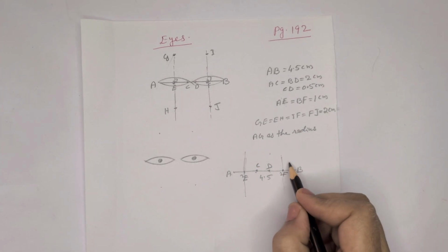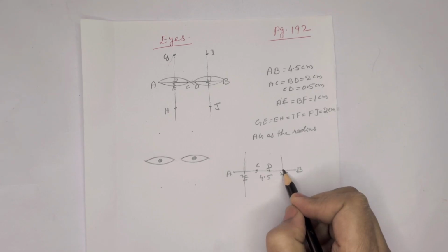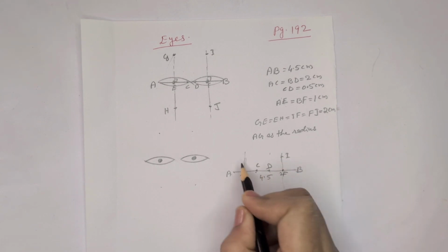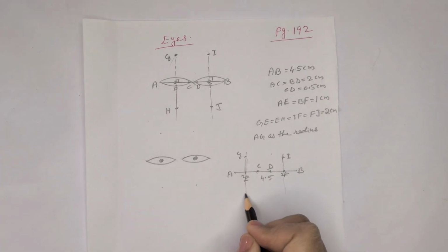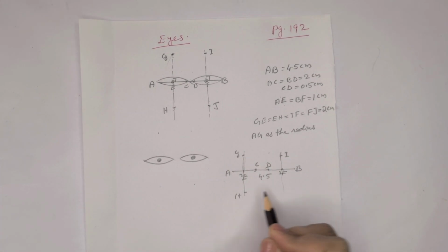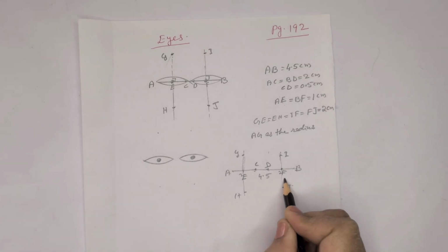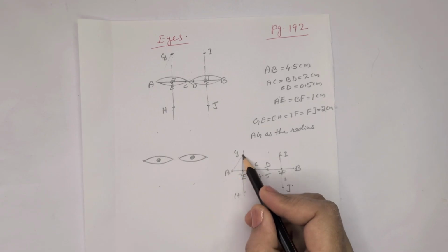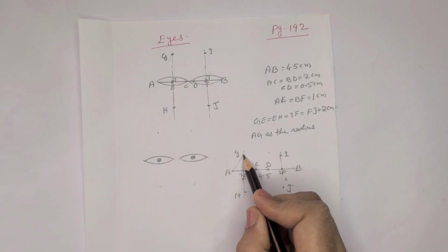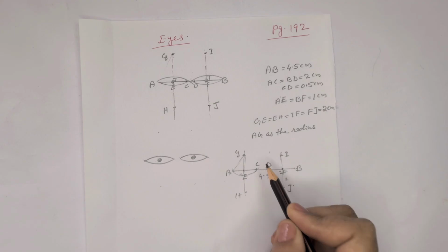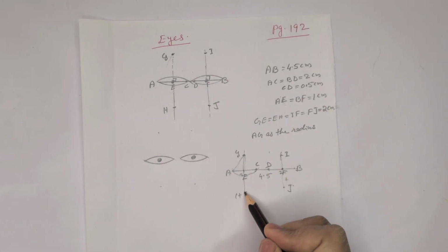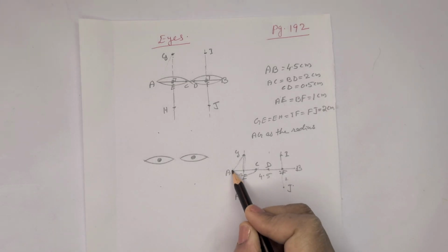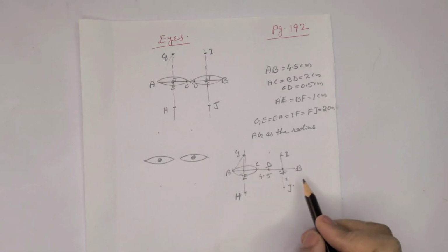And then in this line, here we have to take 2 centimeter up. Mark the point I. Here the point G. Down, that is H. Here J. 2 centimeter. Then take AG, this distance as the radius. From G, draw an arc. It will go like this way. Same from H as the center, same radius. Draw an arc like the same.